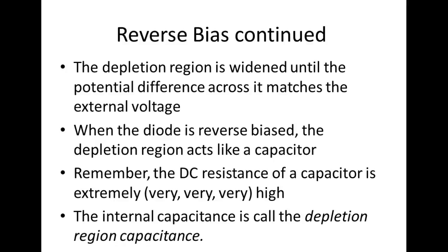So there is current flow through it. If I open a switch, there's no current flow through it. If I close a switch, if it's good, there's no voltage drop across it. Everybody understand that? This is not a switch. It's a semiconductor, a doped semiconductor. So it will never drop 0 volts when it is forward biased, and it will have leakage current when you do what? When you reverse bias.